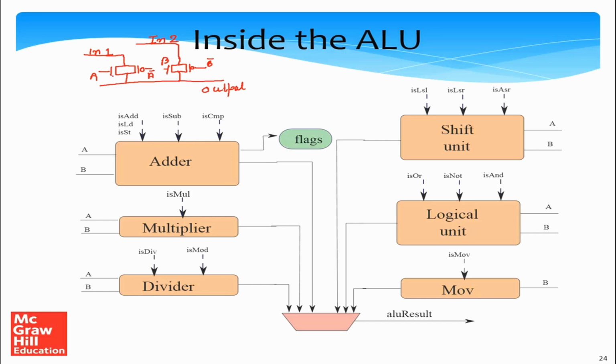So all that we need to ensure is that A and B are not on simultaneously, and that can be ensured by the control unit. Pretty much don't make A and B on simultaneously. So assume that this transmission gate A is on, in the sense the switch is closed. Then input 1 is the same as output, and if B is off, then input 2 is kept floating. So it'll be absolutely disconnected from the output.